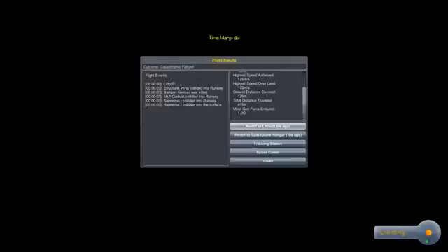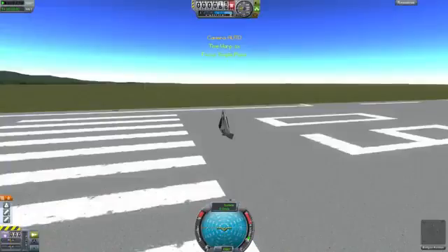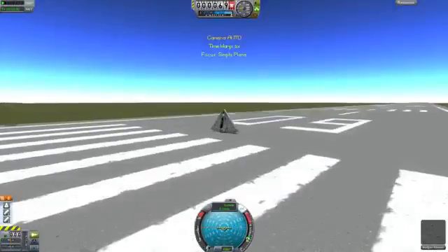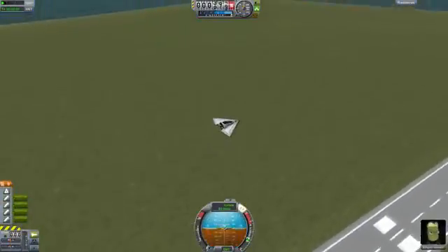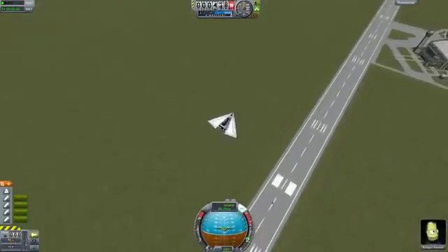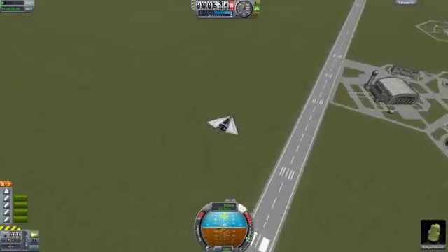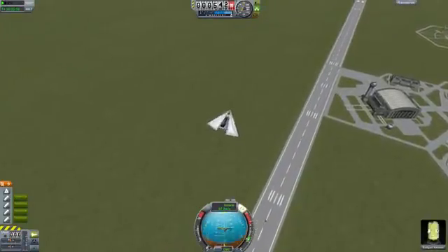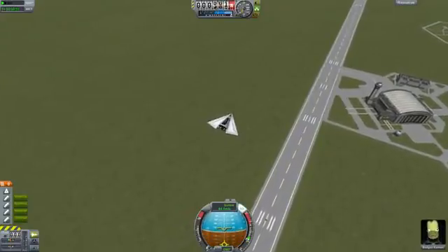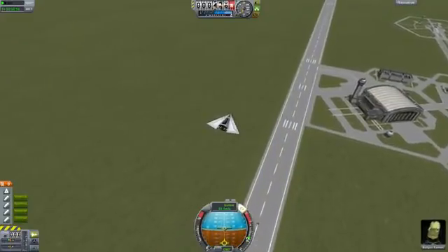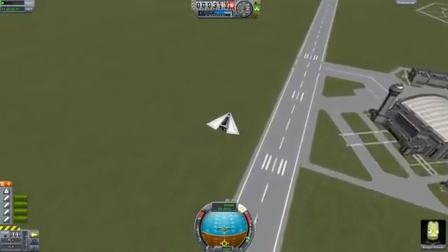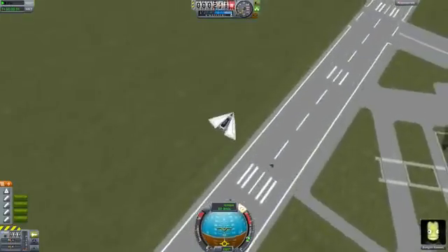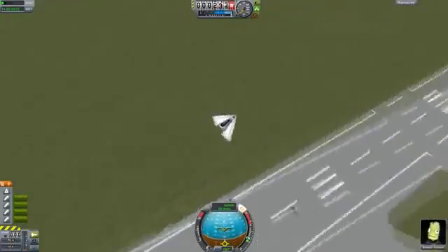This time I'm going to press T to enable stability control. So, stability, go. And actually, we fly more or less straight. But as soon as I turn, whoa, the thing just pushes very quickly in one direction or the other. In fact, I have to push quite hard to get it to turn. And the reason is it wants to push itself away from that velocity vector. What we've got here is an unstable aircraft.